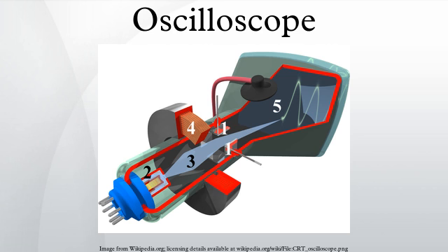A sampling oscilloscope can display signals of considerably higher frequency than the sampling rate if the signals are exactly, or nearly, repetitive. It does this by taking one sample from each successive repetition of the input waveform, each sample being at an increased time interval from the trigger event. The waveform is then displayed from these collected samples. This mechanism is referred to as equivalent time sampling. Some oscilloscopes can operate in either this mode or in the more traditional real-time mode at the operator's choice.